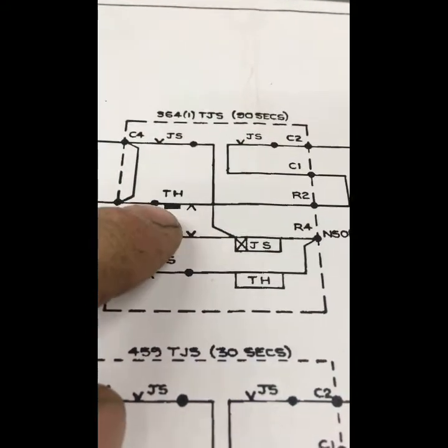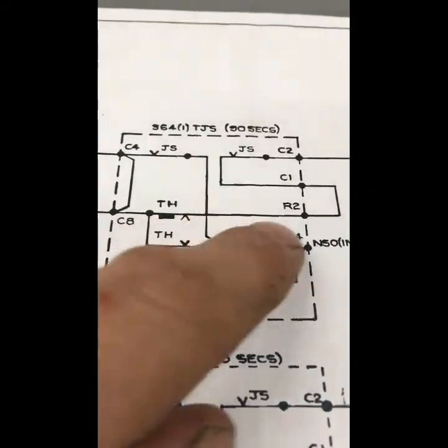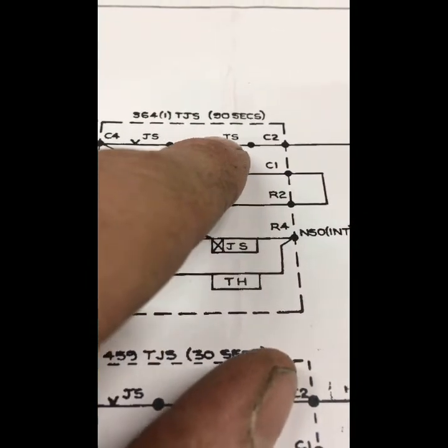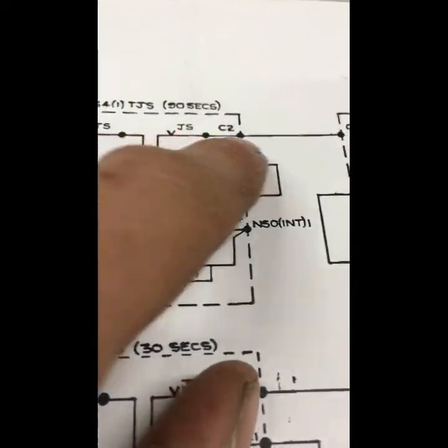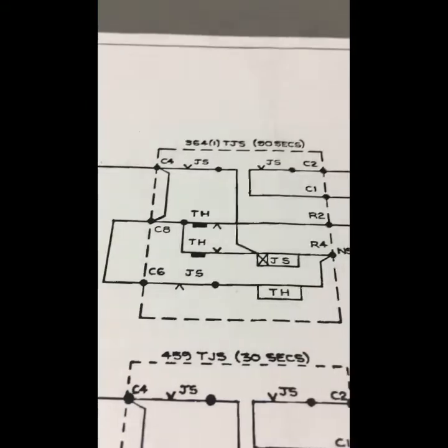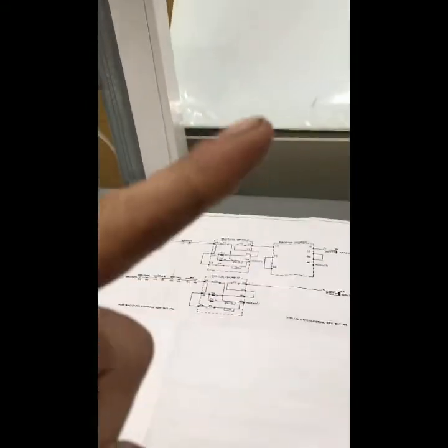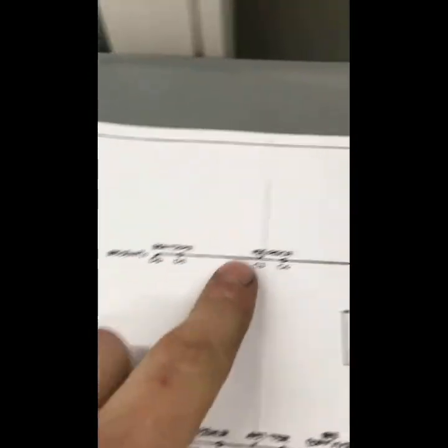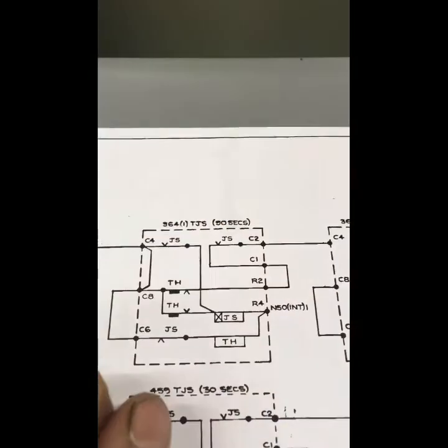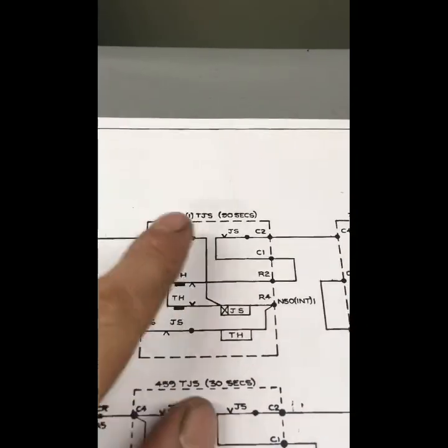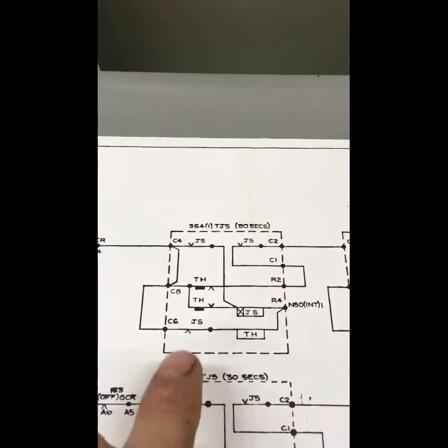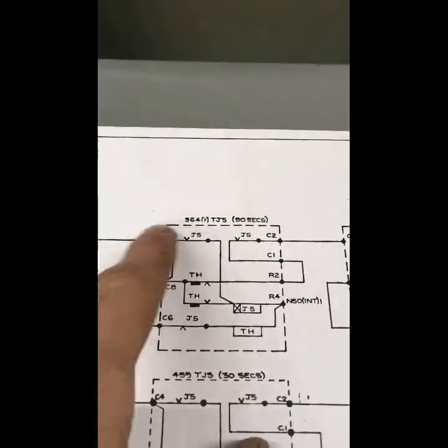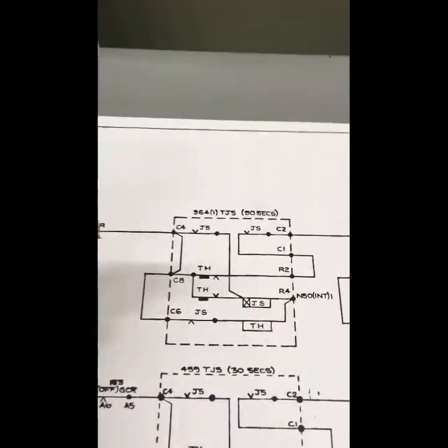And as it makes its back contact again, it makes its output. JS is already held, it's picked and sticked, and off it goes, it makes its output circuit. So it's proved that it was timed and reset. Now when we break any of the input controls again, the whole thing starts again. The JS de-energizes, contact breaks, and we start again, back contact makes, we're ready and set up for timing again, and so forth and so forth.